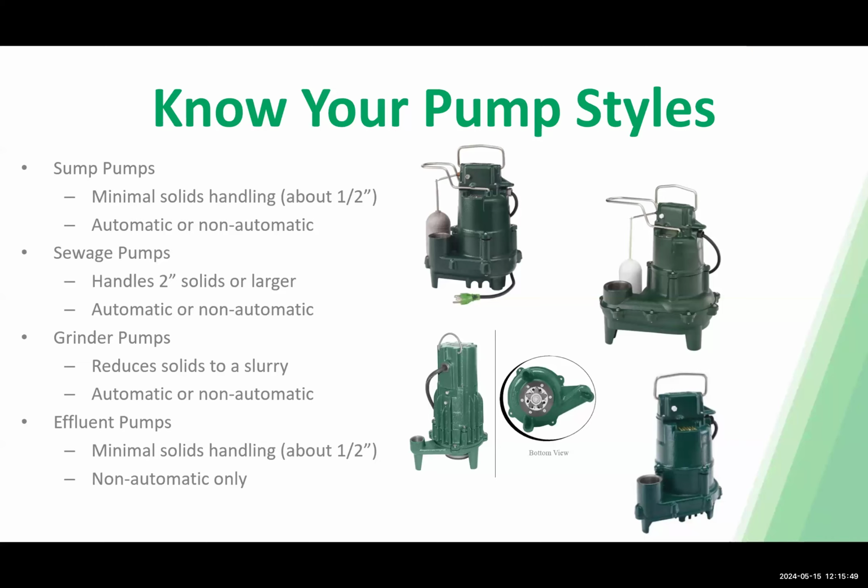But one of the things that you might need to consider there is, in your weeping tile application, how much solids are you probably expecting? That's probably going to determine the level of pump that you need. If you need a solids handling pump that's handling larger debris, you've got stone or anything that you're expecting. But in general, that's probably your decision point there.